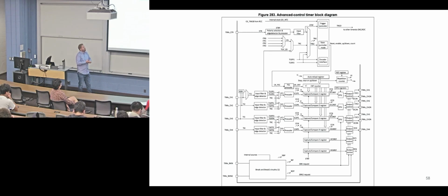There are weird cases where, like, servo motors, the data sheet requires certain pulse widths and they're not compatible with each other. There's a good reason to have a different timer. Servo frequencies could also be noticeable, like the blinking of LEDs, if you had the same period. So those are some reasons why you might not want to use all the capture compare registers in one timer module. Okay, so we're going to go to a worksheet next.